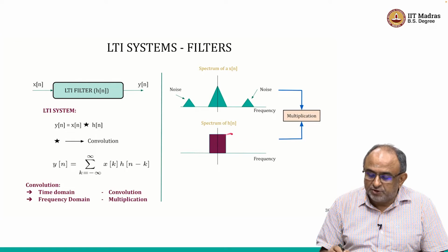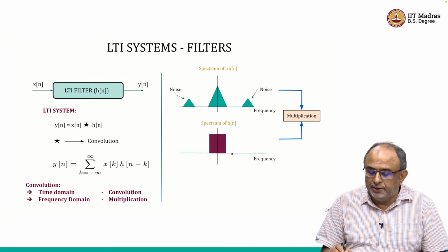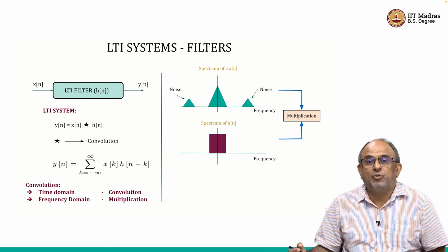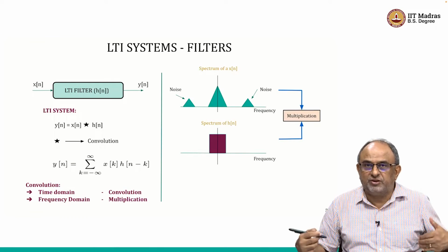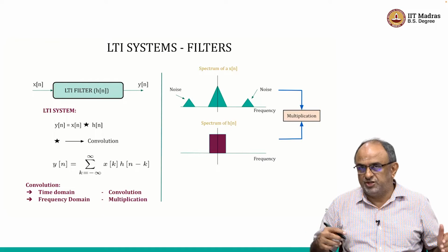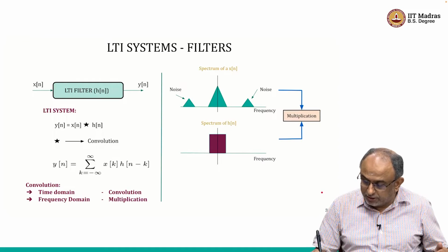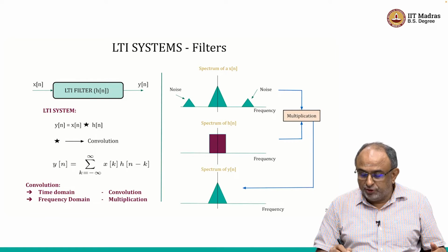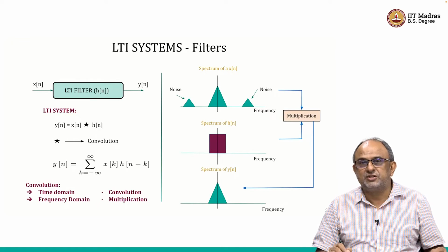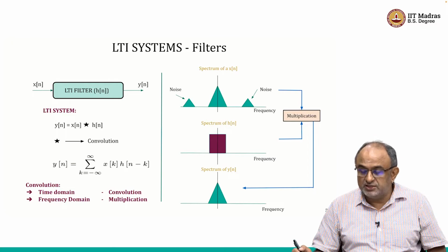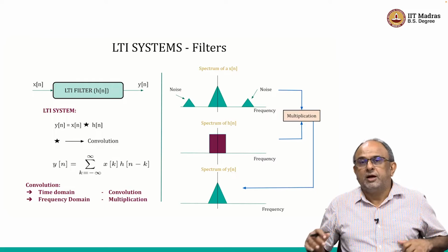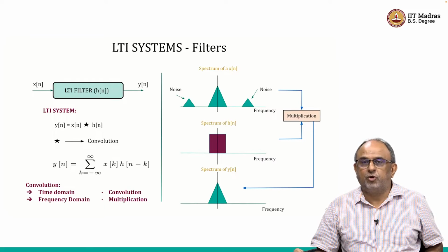That is essentially the filter that we desire. This is the spectrum of our desired filter, which passes the brown region with unity magnitude and all the other parts with 0 magnitude. That is basically when we design a system, we make these specifications: it should be 0 in this region, it should be unity in this region, and so on. And if I do the job properly, the output will be only the desired signal, which is the big triangle. The two small noise triangles will be removed. And so, when I am talking, after you filter, it will be perfectly clear voice.